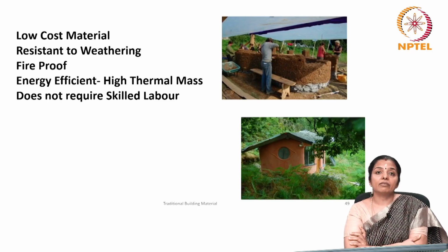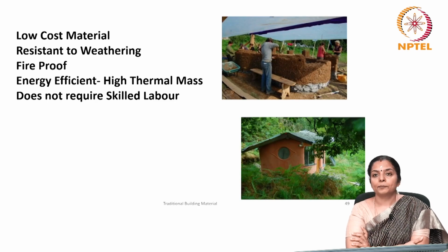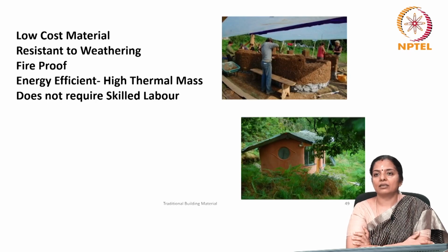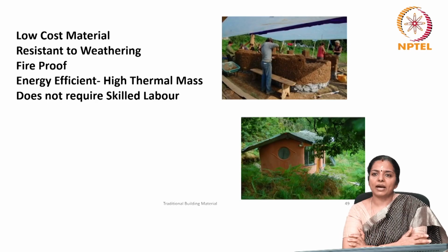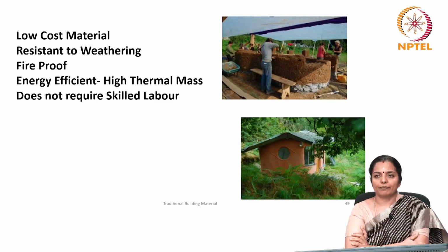These buildings are very energy efficient. The walls of a cob house are generally about 24 inches or 2 feet thick, and the windows are correspondingly deep set, giving the homes a characteristic internal appearance and making them ideal for passive solar construction.